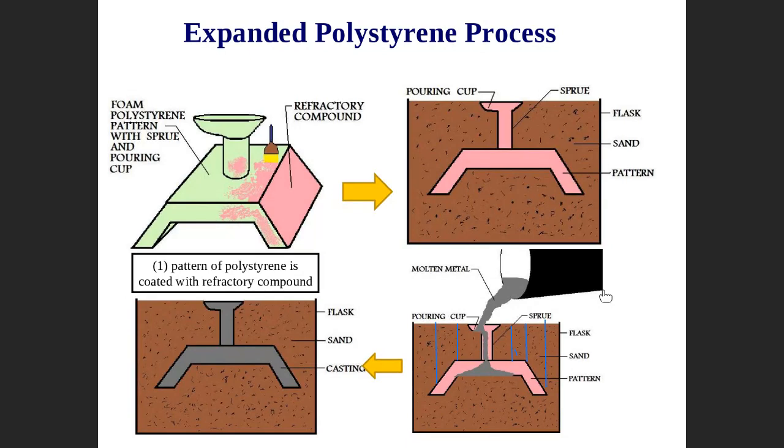And for this reason, you must create cope and drag, two parts, and assemble them, so it is really complicated. But here, you just put the pattern inside and no need to take it out, so you can make highly complicated parts. That's why it is really very important.